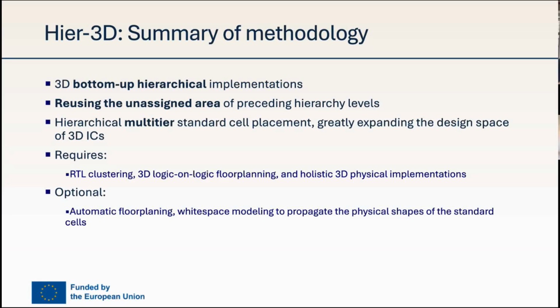In order to enhance the methodology, it is also possible to add one automatic floor planning step, and also it's possible to add some improvement in terms of the definition of what is white space, so that we can get a trade-off between the possibilities of recovering the space that we have in different iterations without having to create a much more detailed LEF file.